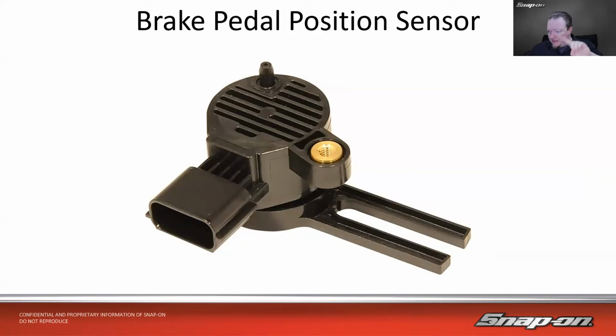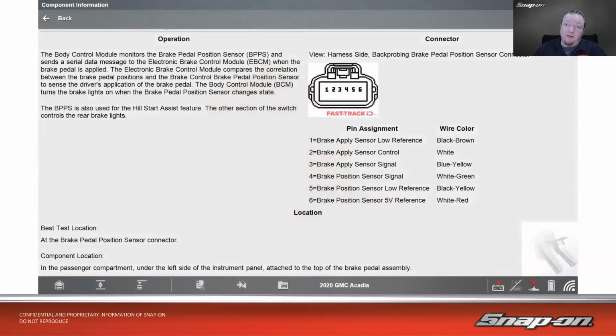Basically a rheostat, kind of, in a way. Pot. Think about it kind of like a throttle position sensor. It works on the same principle, right? It's got varying voltage across or varying resistance and changes the voltage output. So this would ride on a piece of the pedal, maybe the rod or whatever, and then it's going to output to the modules that need it.